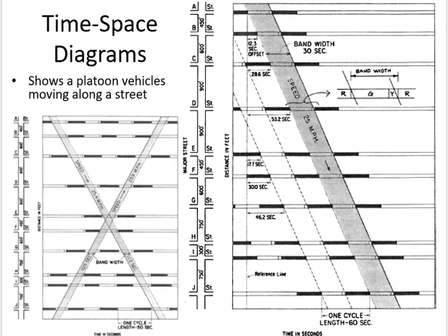But the problem with two-way coordination is I cannot use the entire time. You can see here, in one-way I'm using the entire time, from green to end of yellow. In two-way coordination, am I using the full green? No. Same thing on the other side as well. It starts from the start of green, but now I cannot go to the end, because I have to look after the other direction as well. So I have to make the green signals in a way that both directions are going simultaneously. Or make a bridge. Yes.